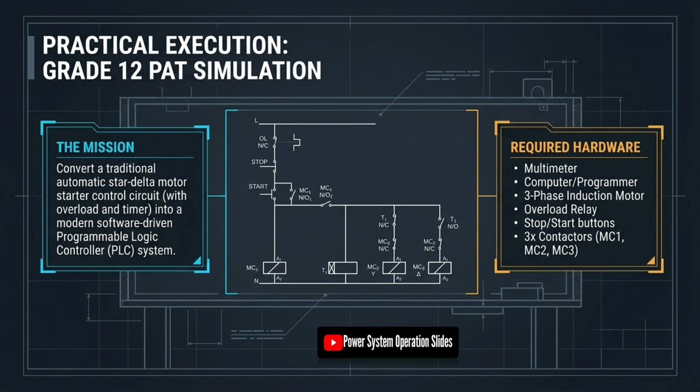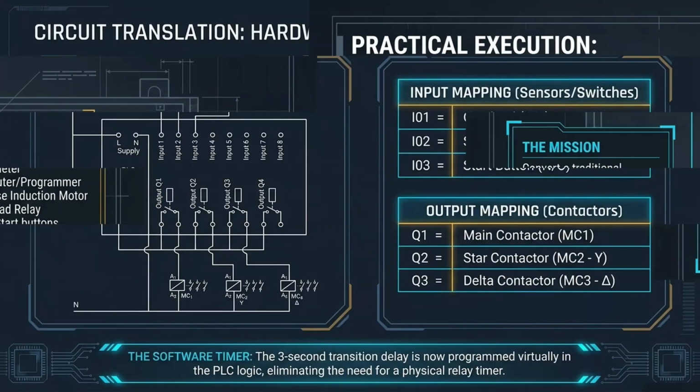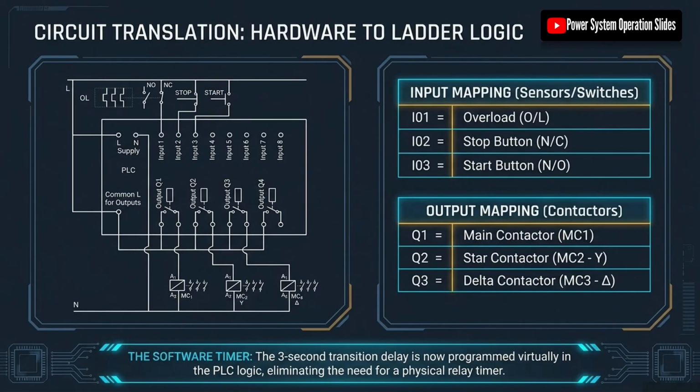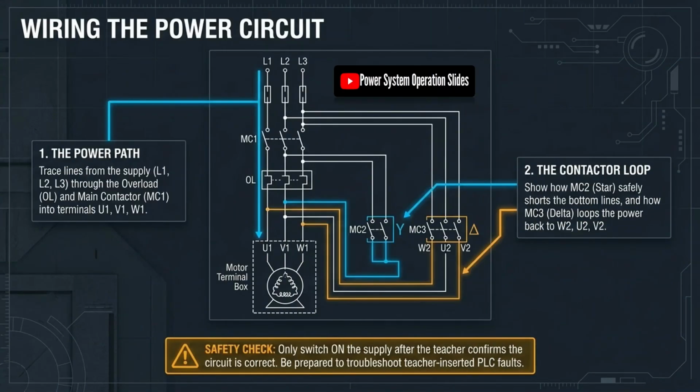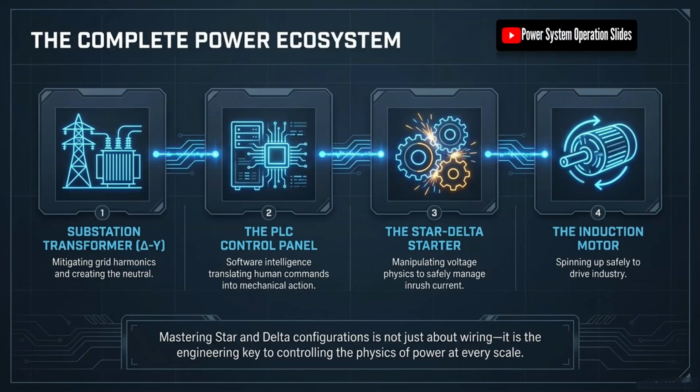The selection between star and delta should therefore not be considered as a simple decision about which configuration is better. Each connection provides specific technical characteristics that make it suitable for particular applications. Star is particularly useful when a neutral point, grounding reference, and multiple voltage levels are required. This makes it highly suitable for distribution systems serving a combination of three-phase and single-phase loads. Delta is particularly useful when full line voltage must be applied across phase windings, when heavy industrial loads are involved, and when harmonic containment is beneficial.